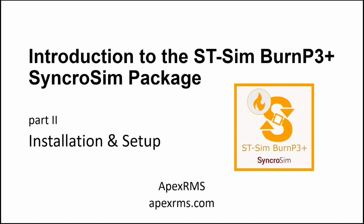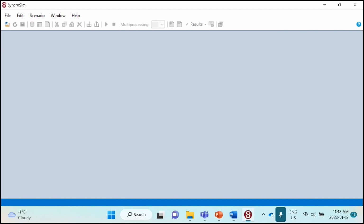Now let's go ahead and open SyncroSim. I'll be walking you through the package installation and setup. So we'll need to install 4 packages to run an ST-Sim BurnP3 Plus model. We'll need the ST-Sim and BurnP3 Plus base packages, the BurnP3 Plus Cell to Fire add-on package, and the ST-Sim BurnP3 Plus add-on package. So first we want to check which of these packages are already installed.